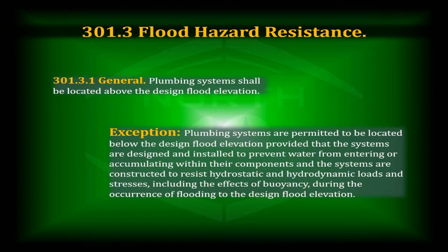And those standards basically say we want to keep the flood waters on the outside and the sewer and drainage waters on the inside, and we don't want to have those things intermingle, but we also don't want the stuff to have the effects of buoyancy or floating, which obviously could strain the system, break the system, and we don't want these things to be susceptible to the hydrostatic and hydrodynamic effects of the floods, which are the crushing and expanding effects of the floodwaters. So if you can put it down in those areas, then that means it has to conform to all of those ideals.